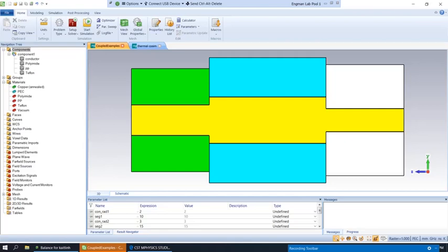In this tutorial we're going to be covering how to complete an EM thermal coupled simulation. And so what we have here is the coaxial connector that we created in a previous tutorial. We're now going to create a coupled simulation to simulate what happens to this connector in the electromagnetic domain and then take the heating that is produced from those electromagnetic sources and simulate how much heating this coaxial conductor experiences by doing a thermal solver simulation.